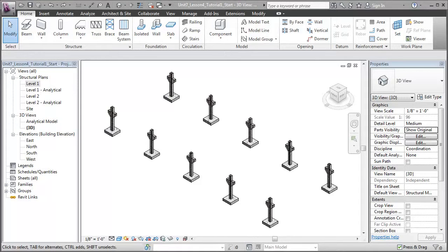Prior to the introduction of the new Assemblies feature in Revit 2012, we might have created a group containing the column and the rebar elements and duplicated this throughout the project. This is a good solution for repeating the geometry, but still has a few limitations. Groups cannot be included in schedules, so we'd have to come up with another way to tally those grouped elements. Also, any views that we'd create to describe the details of the column and the rebar would be embedded in the model itself, which clutters things up and makes them harder to find.